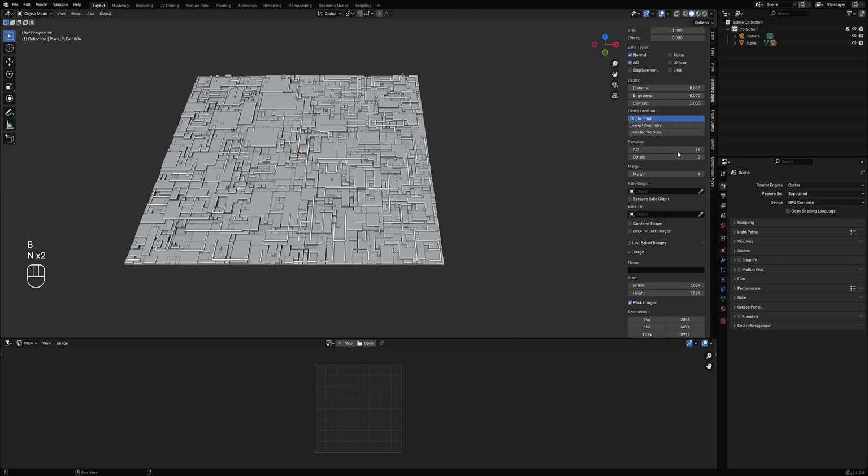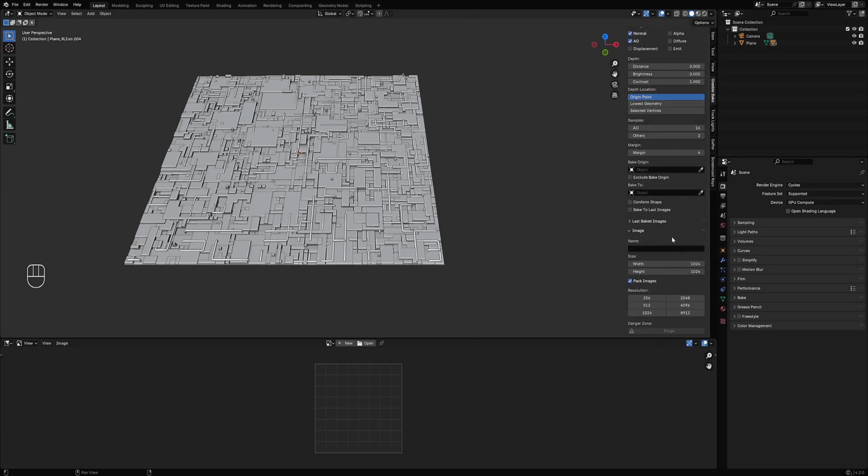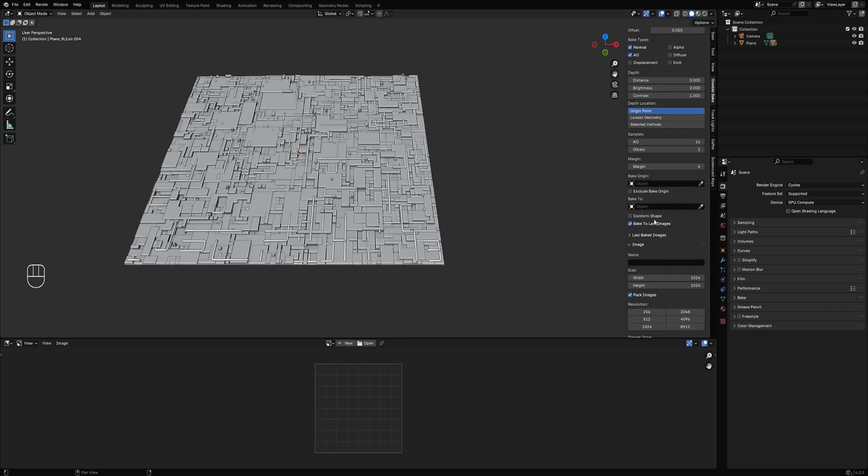Okay, so let's bake this. Let's go to Greeble Bake, and turn on Bake Select Images. Do not conform to shape because we're just using the primitive plane, which is the default shape. And let's use normal, AO and displacement. For the AO, let's just use 16.